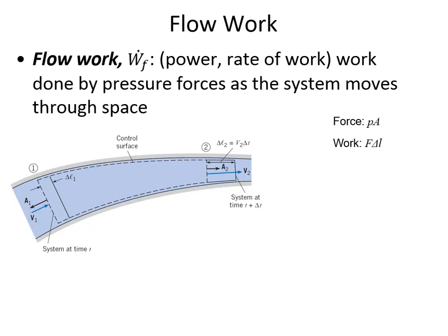We've got a control volume that is the dashed line at time t. The water inside of the control volume is the system. Remember that a system is a continually connected stream of particles. So inside this pipe element that has a changing diameter, we've got a certain amount of flow that's moving towards the right. And in a time increment at t plus delta t, the control volume changed. This control volume is continually enclosing a certain number of particles. The system is moving, and so we can move the control volume if we want to.